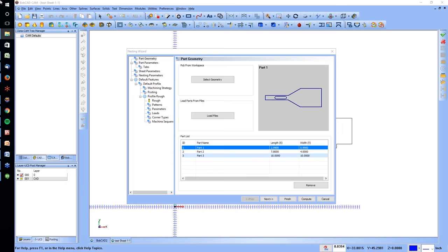I'm curious how sheet size and material are taken into account. Does it correlate with the material specifics in SolidWorks? No, it does not. Because you're not actually bringing in your SolidWorks file, it doesn't have those options. It doesn't read the material, it doesn't read the type of material, anything like that. You're bringing in a flat 2D part, so it's not going to have any of that data.